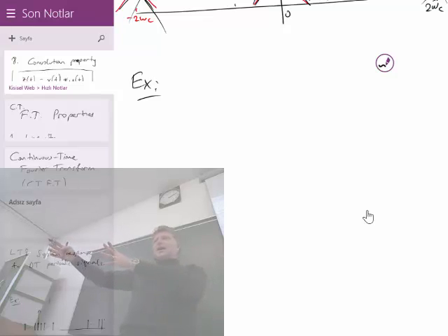Suppose this is the high frequency or band-pass range. You just pull it to the low-pass region, around the DC, and then apply a low-pass filter, which is very nice, as I repeat, and then push it back to its original place. That would mean, effectively, a very nice band-pass filtering, isn't it? So that's what you can also do.